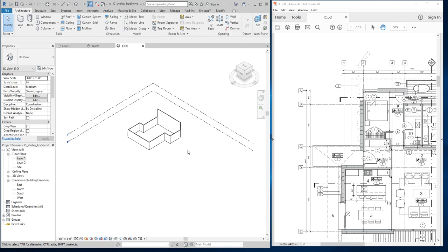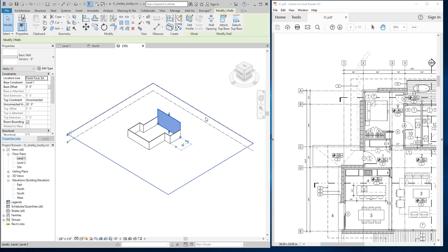In Revit, I actually have kind of a sense of scale on the screen, but what I don't have is a sense of verticality. I don't know how tall it went. And so I draw things and I immediately pop into 3D and look and see if they're correct. And if you see something like this, I'm going to select it and I'm going to say, oh, I forgot to set a top constraint. I'm going to change that to level 2, and it's as easy as that, okay?